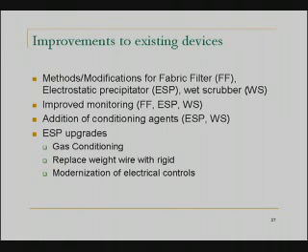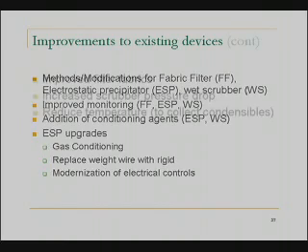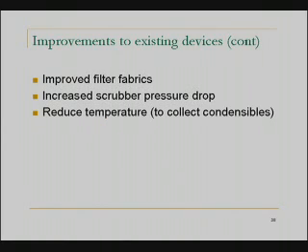Those types of things can improve the performance of these devices. For fabric filters, improved fabrics can sometimes lead to better performance and fewer malfunctions. For wet scrubbers, increasing the pressure drop is certainly a way to improve the performance.